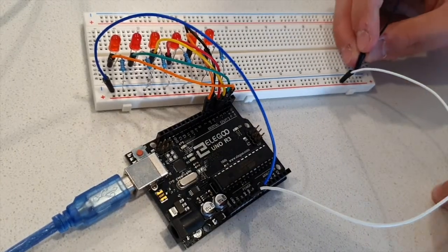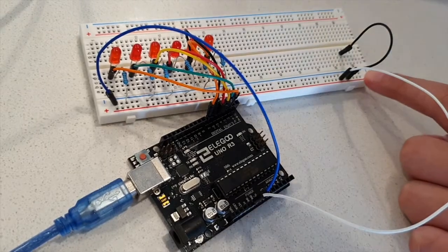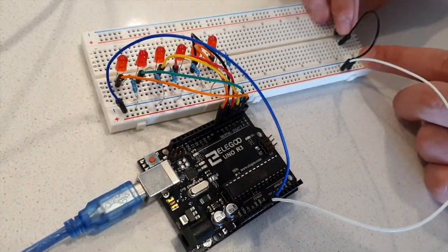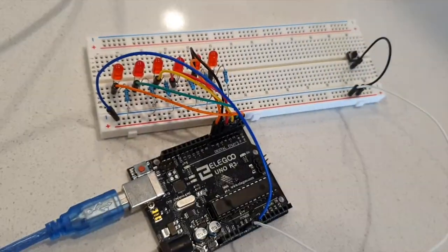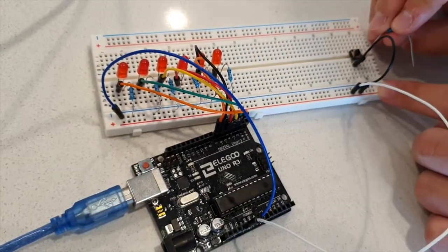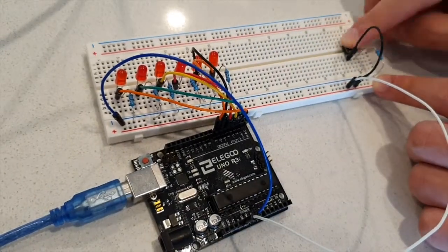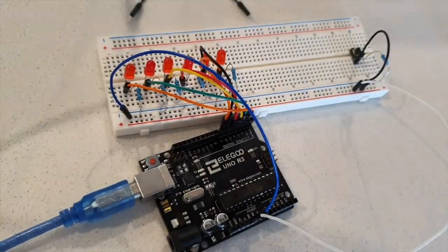After that, I will want to set up the button as our main source of input. The button is important because it lets us essentially control the flow of electricity as a switch. It lets us turn things on and off with a binary input. In this case, we will set up the button by connecting it to the 12 pin, along with connecting the 1000 ohm resistor to it.